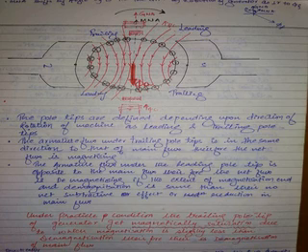But the flux is cross-magnetized. You can't have the same flux like this now. This is the flux in the machine when there is no armature flux. But when the armature flux comes into the picture, this flux won't come like this, but it will get distorted, disturbed, cross-magnetized. Why cross-magnetized? If you observe here, there is a demagnetization in this region, as well as demagnetization in this region. So the net flux won't flow like this and like this, but there is magnetization in this region. The lost flux here came here, the lost flux here again came here. So here the net flux density has been increased in this trailing pole tip.